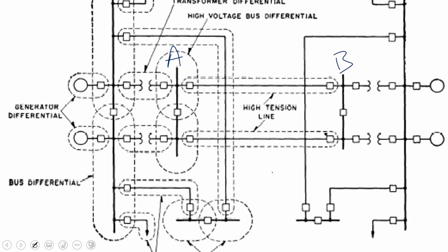The relay, based on the contacts that are used, and you would be familiar with your normally closed and normally open contacts and all of that fanciness, then energizes an operating arm on the breaker. So the fault current doesn't pass through the relay. That contact then energizes the operating coil on the breaker, which then operates the breaker.